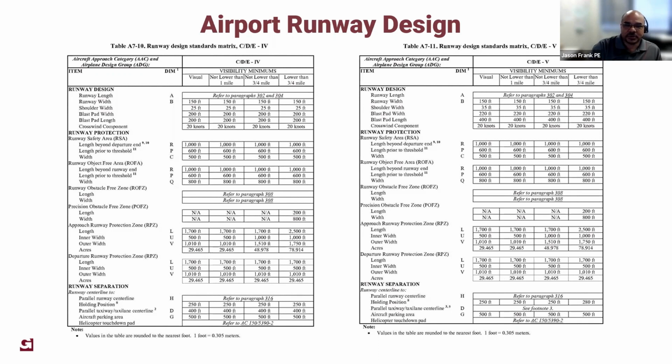light, approach light, or an instrument landing system. Those are items that are fixed by function. They're frangible. So if an aircraft did come in short and a wheel gear caught them, they would easily break off and reduce any potential damage to the aircraft. Or if it landed long, it would skid off towards the end of the runway and be able to knock those lights over easily, again, not causing too much damage or any damage to the aircraft.